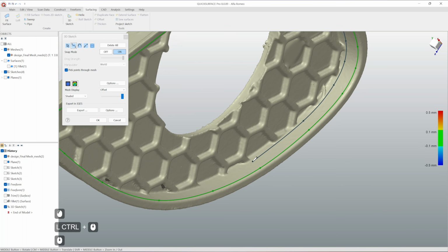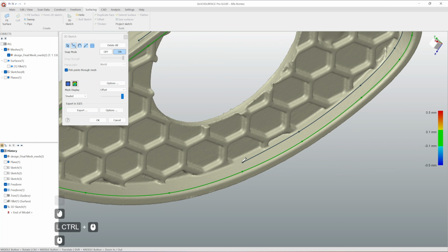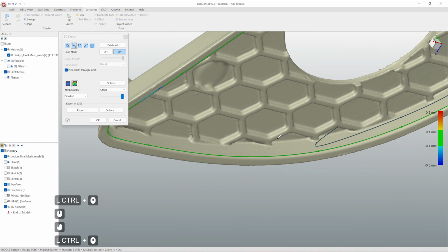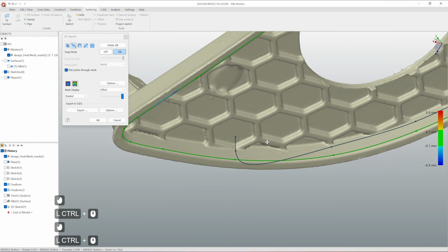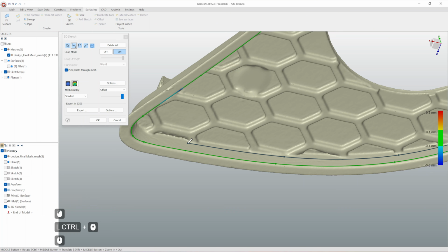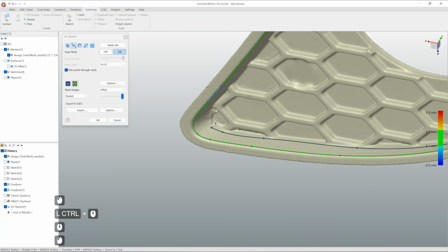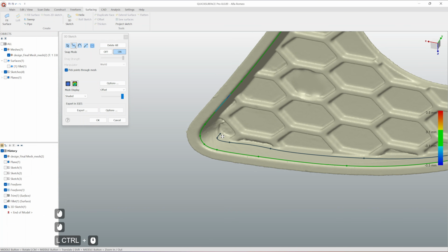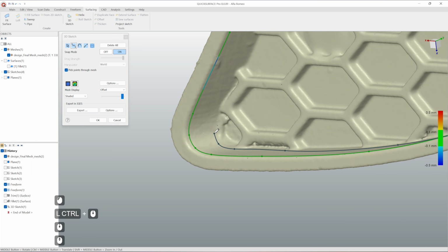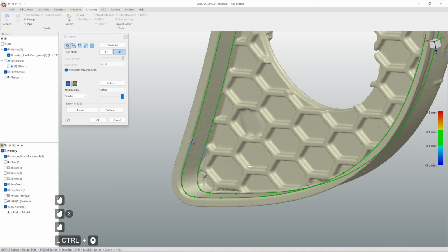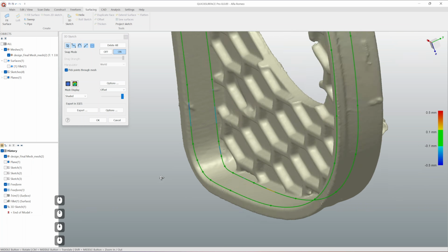Simply, if we don't have the same amount of vertices, it might start to twist somewhere and create undesired results. But in these cases we can also create additional guide curves to compensate for this and to get rid of unwanted results. Okay, so something like this.